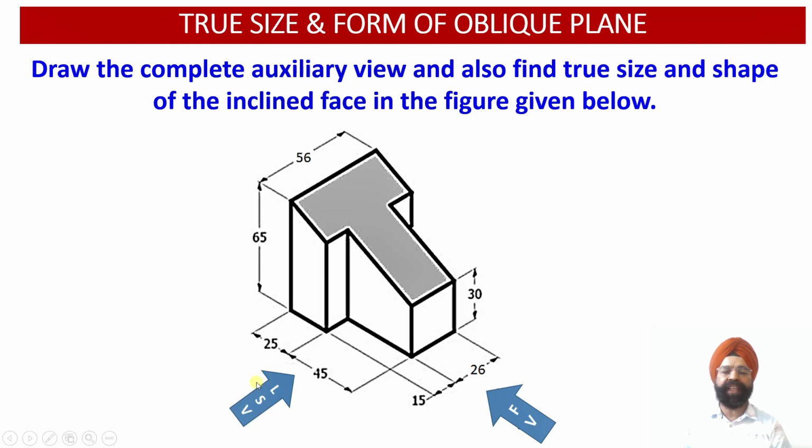We can check over here that we will be getting this edge view of the section top surface of the solid in the left hand side view, because in the left hand side view this entire surface will be visible to the observer as an edge view. Besides the left side view we are also going to draw the front view of the solid, and then by using the information available through the left side view and the front view, we are going to draw an auxiliary inclined plane which will be parallel to the sectioned inclined cut surface.